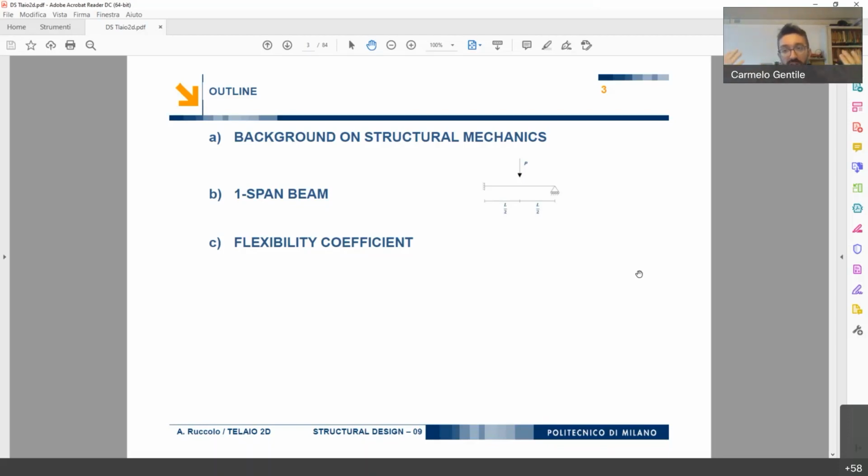So we know how a structure behaves. We don't know how to solve a structure just by looking at it and snapping it. It takes time, and that's why we use software. But we also need tools to control what the software is actually doing, and this tool is basically our experience in solving structures. If we see a hinge, we know that there we do not expect any bending moment.